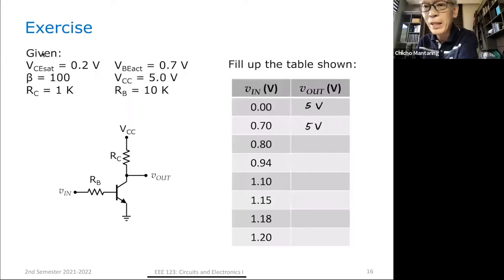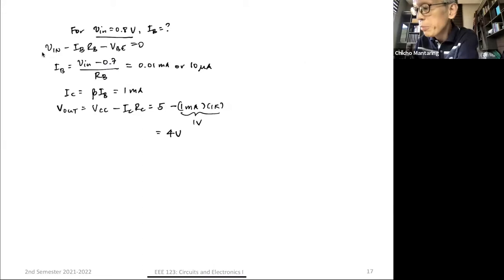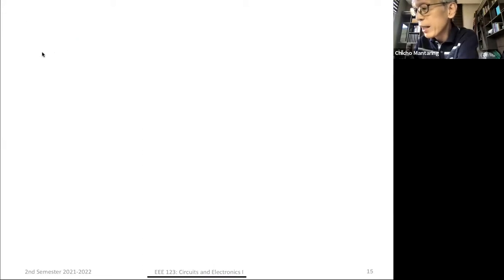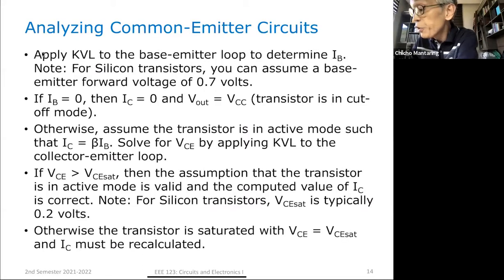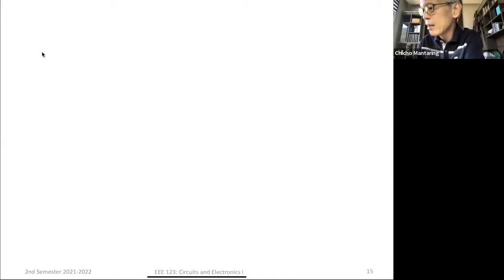Okay. Are we done? Check. Don't forget that step. After you compute for VCE, check if VCE is greater than VCE SAT. You always perform this check. Is VCE greater than VCE SAT?